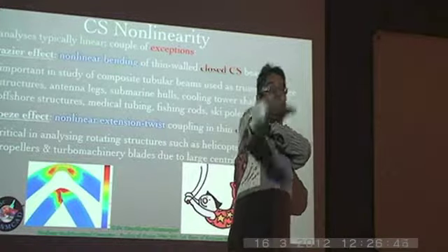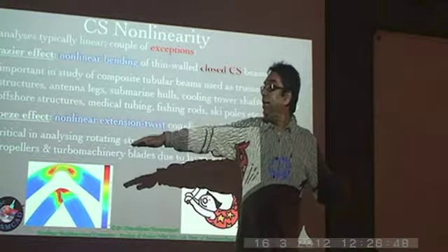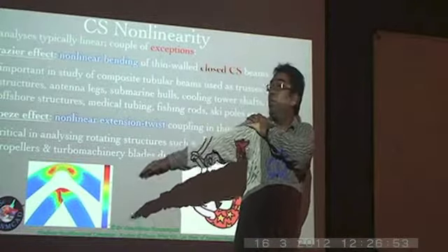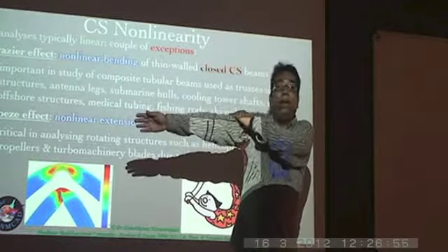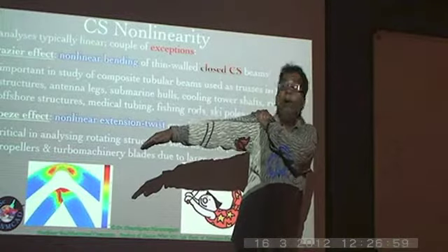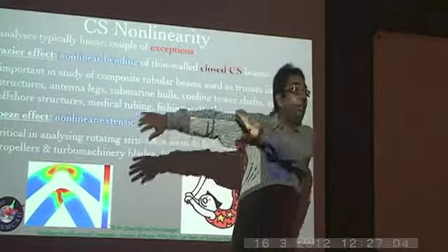What I told you is just the bending, but aerodynamically speaking, the bending and the twist are coupled. It is the change in the angle of attack which changes the lift distribution, and therefore there is a coupling between the lift and the twist.